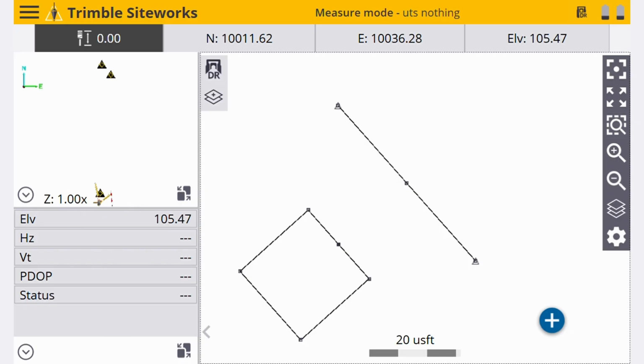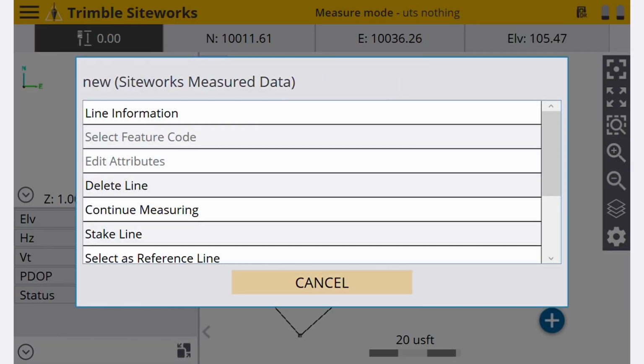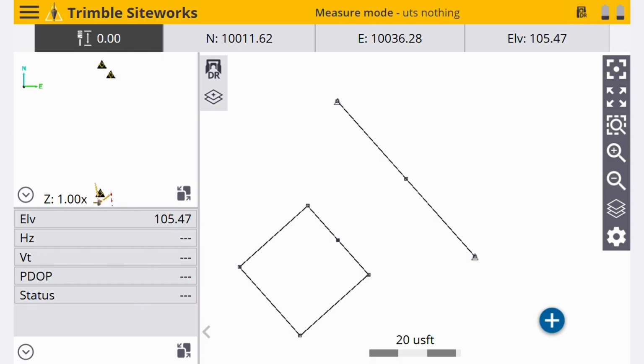In the last videos, we had shot our corners, which were control points, so that we could build multiple times and always have the same corners. We had made a midpoint, and then we had bang 90s around our box to make a 20 by 20. What I want to do next is build our Alaskan slab.